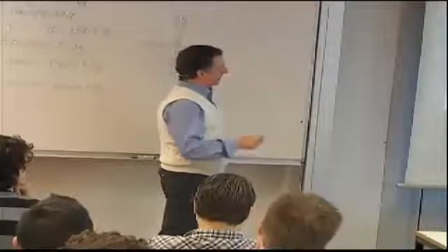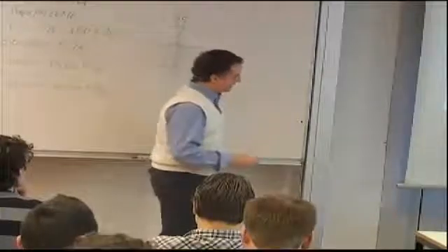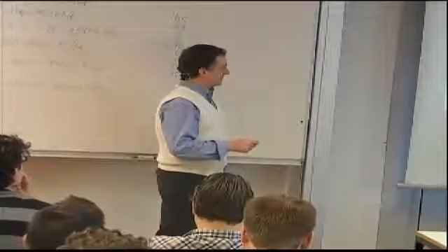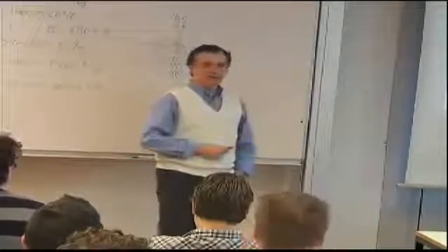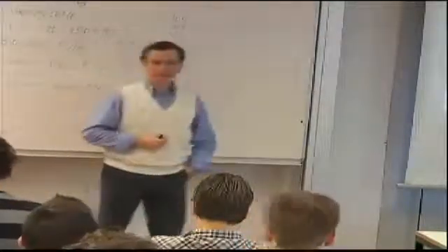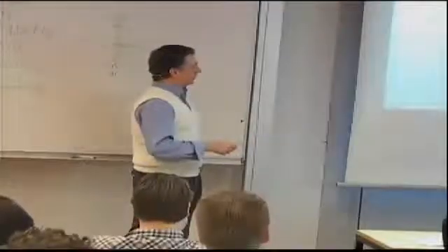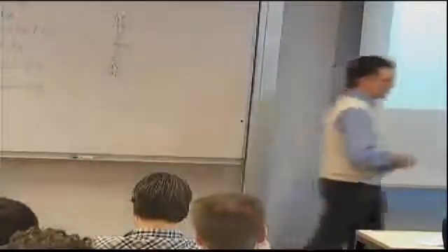The same for the second equation, which would only involve U and V again, but because of the B matrix you have this. Finally, the third one, which would have been only a D matrix times W terms. Because of the B, again, it brings in the U and V's. So for one thing, if we're trying to make our life easier, we should use symmetric laminates because the B matrix is 0, and that would make this to have no U and V dependence, and these two to have no W dependence. But good luck solving them anyway. It is extremely difficult, obviously.